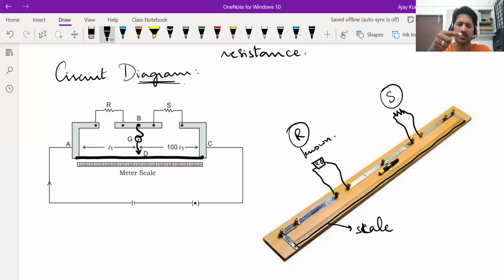Okay. At the other end of the galvanometer, you will find a pencil-like device. It's called the jockey. Using that, you can connect the galvanometer's other end to whichever point of the circuit you want. Okay. So in this actual photograph, if you see, there's this connector. From here, we connect a wire to the galvanometer box. In lab, you will see that galvanometer is a box-like device. Its needle can deflect both ways. It can show you the direction of current also, which way the current is flowing.